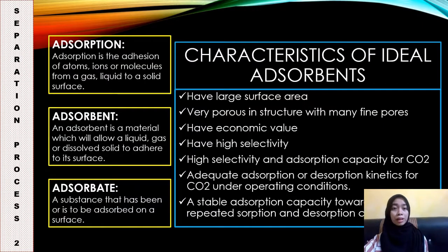On that note, do you know what is adsorption? If you did not know, please read the definitions given here, because I will skip that and explain about the characteristics of ideal adsorbents. The first one is that adsorbents must have large surface area, very porous in structure, have economic value, have high selectivity and adsorption capacity, and adequate adsorption or desorption kinetics for the adsorbate.